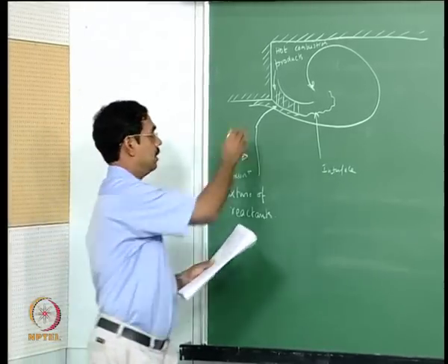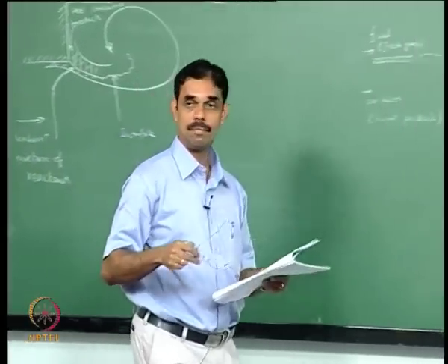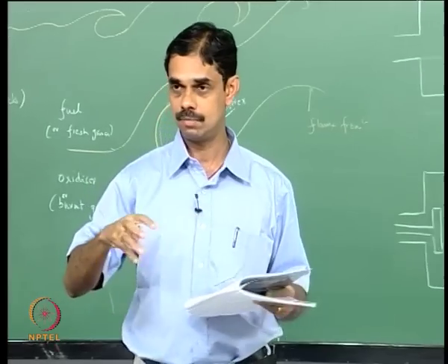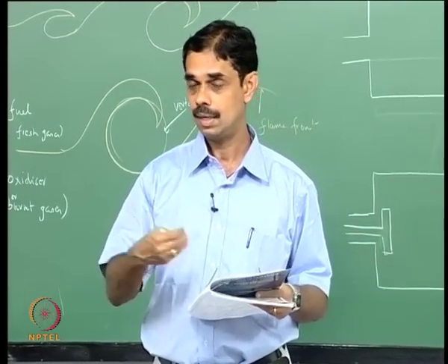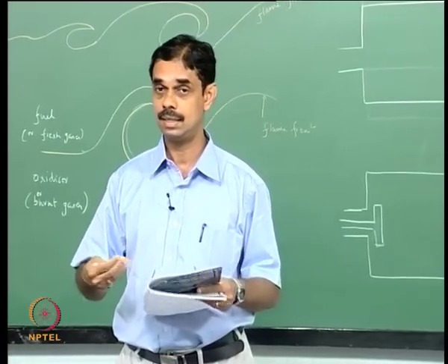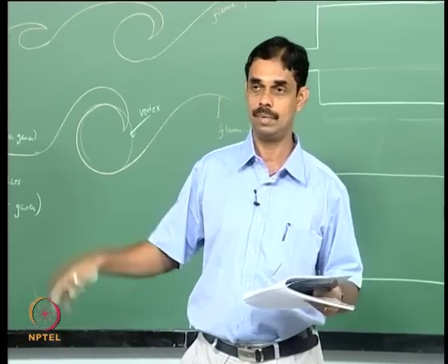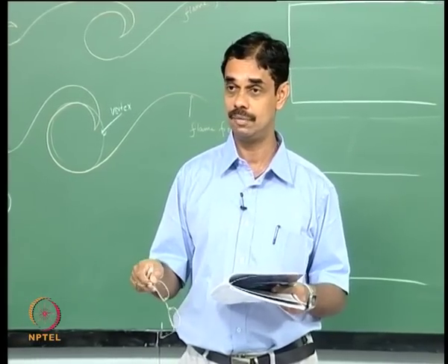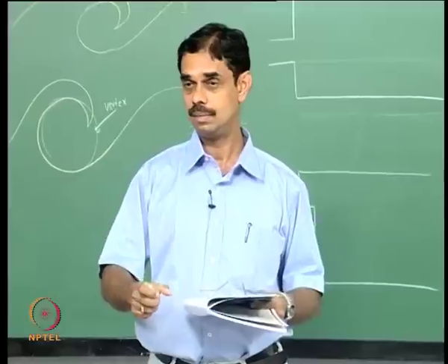So you have a roll up, but in reality that is not the only thing. You will have interaction between vortices because the shear layer has instability that will shed at some frequency. Those waves will have some preferred mode of excitation and so on, and then vortices will be shed, and these vortices will actually merge, and then you will probably end up having a lower frequency of the bigger organized structure, and of course this will be obstructed by the walls and severely interfered by the walls, so that the situation will be quite different from a flow from a jet.